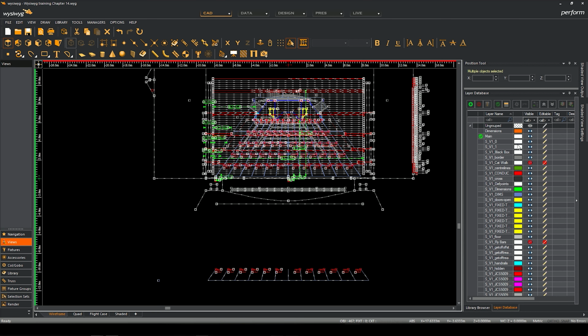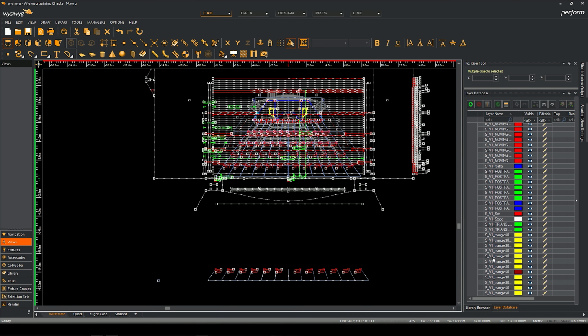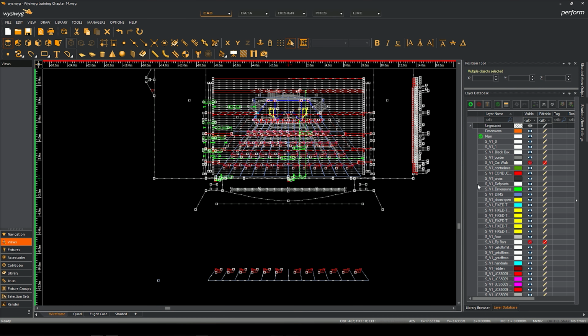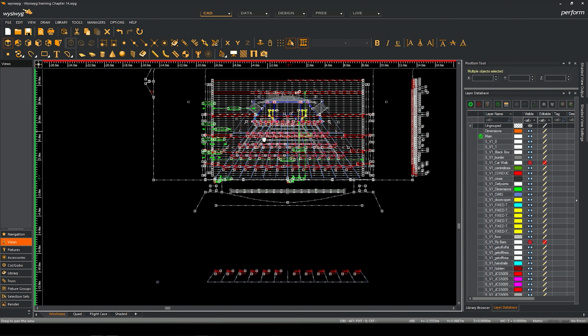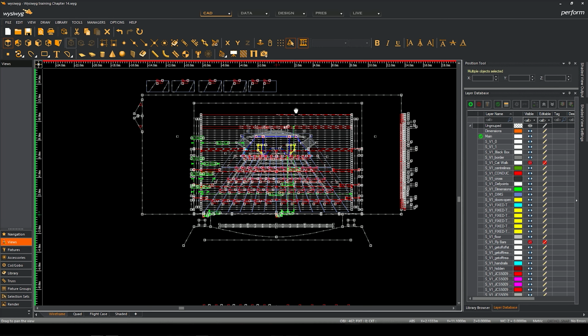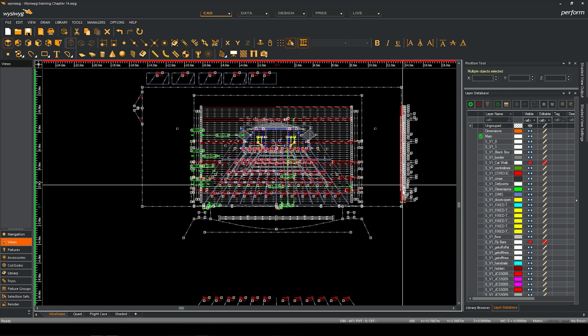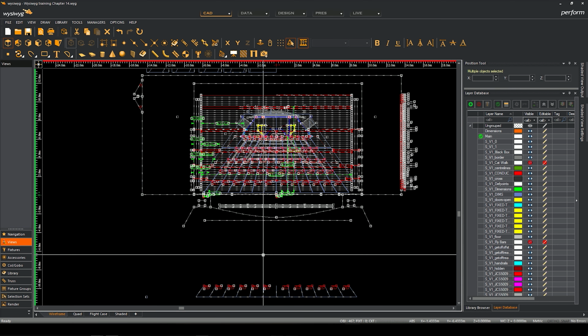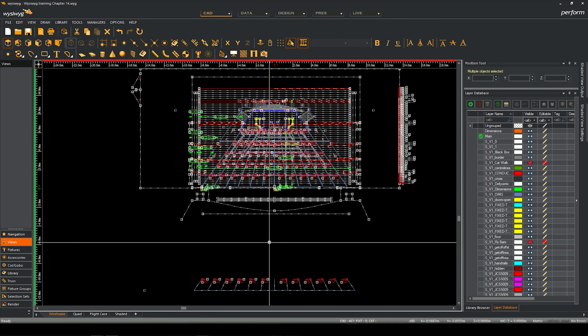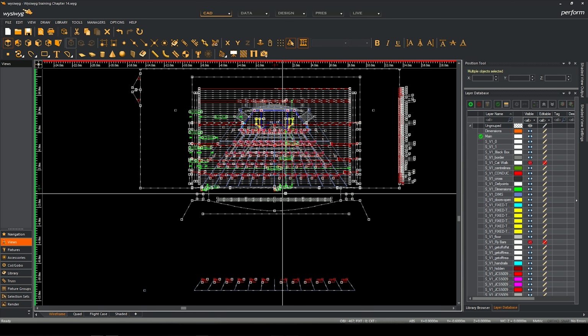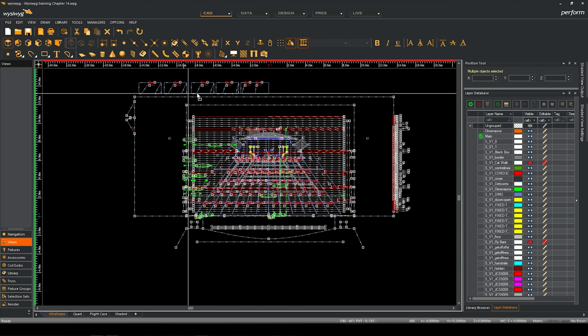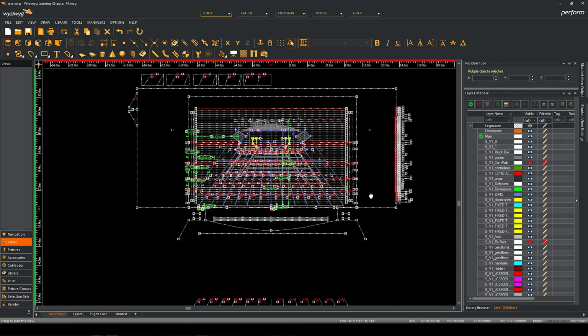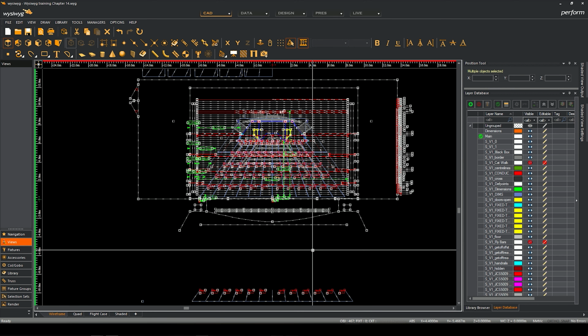So it's imported all those layers, all with the prefix S underscore V1 underscore. When you import something, you get a moment to change it. Everything selected has just been imported. It's actually very hard to get this option back again later. You have to go and select everything one at a time. So if you have a file with lots of objects in it, this could be your last chance to right click and go to properties and make a change if you need to.